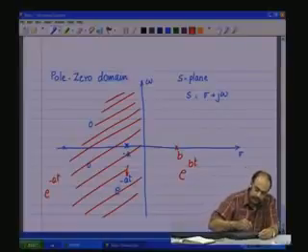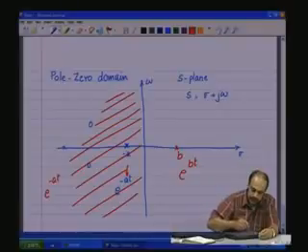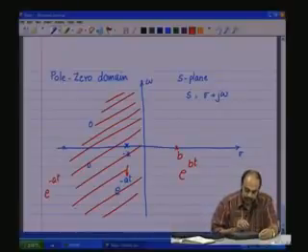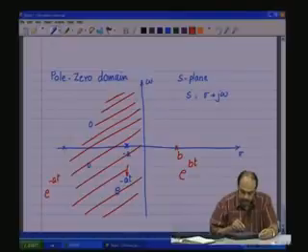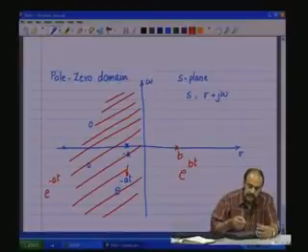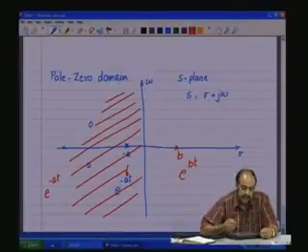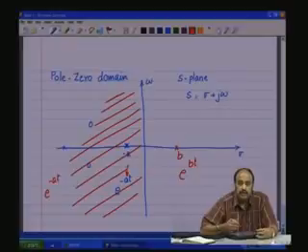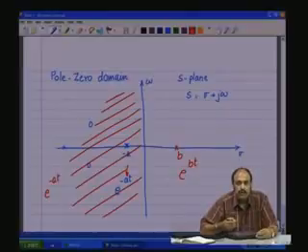So, all physical systems will have poles and zeros located on the left half of the S plane, and how close or far away from the omega axis or the y axis will determine the features and characteristics, the damping ratios, the decaying nature, all those issues which can be used for synthesis of the circuit.